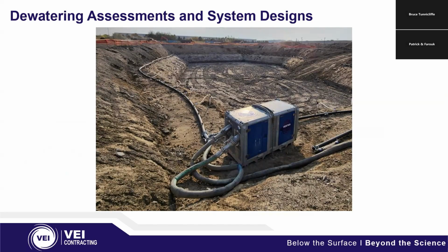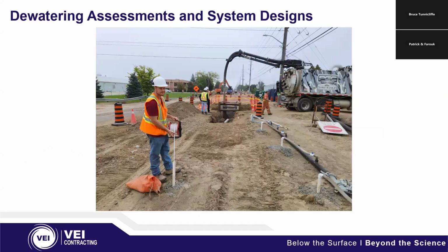I have a couple figures here that just show different types of dewatering in the field. This is a two-stage well point system. They're benched here because the excavation is going fairly deep. But as you can see, pretty dry excavation. You can see access in the top right, so everything is stable and the construction can continue. Another example here, which is probably more common, or when people run into more, is road reconstruction. Again, it's a well point system, but it's a linear infrastructure. So these can be turned on and they move forward as the project continues.